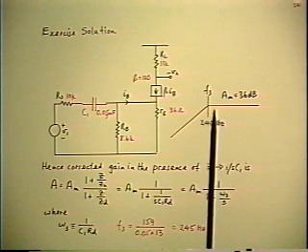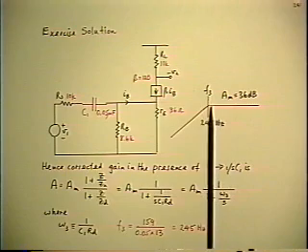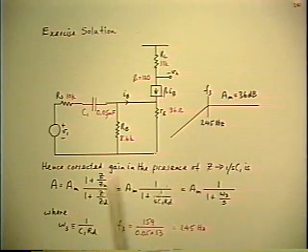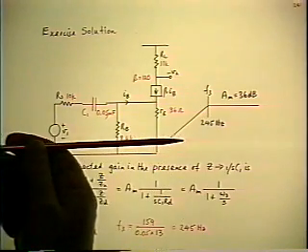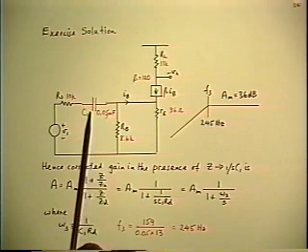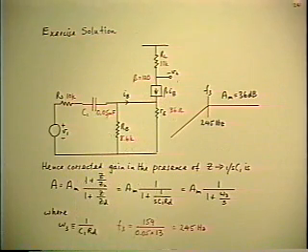So the frequency response is the reference gain at infinite frequency, and as you come down, the coupling capacitor starts to open up, gives you an inverted pole and a drop-off of the gain, and the gain goes to 0 at 0 frequency. It doesn't flatten out anywhere because the capacitor goes to infinite reactance at 0 frequency and, of course, disconnects the output from the input.